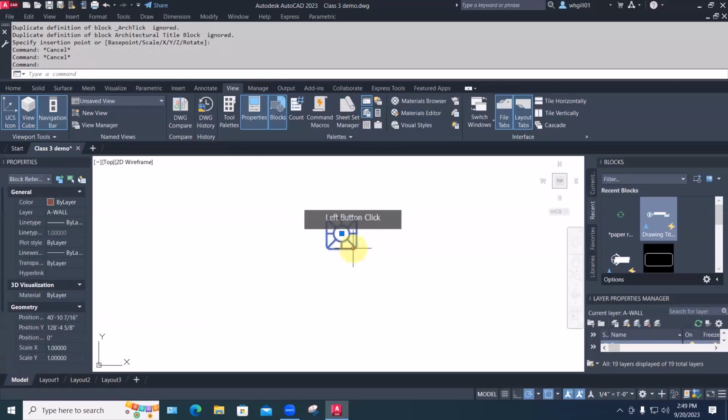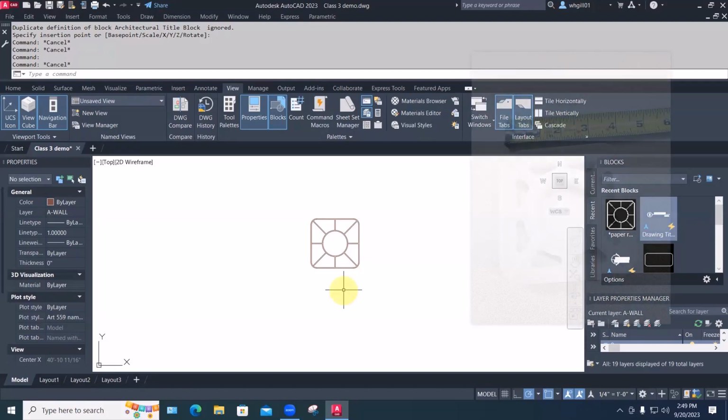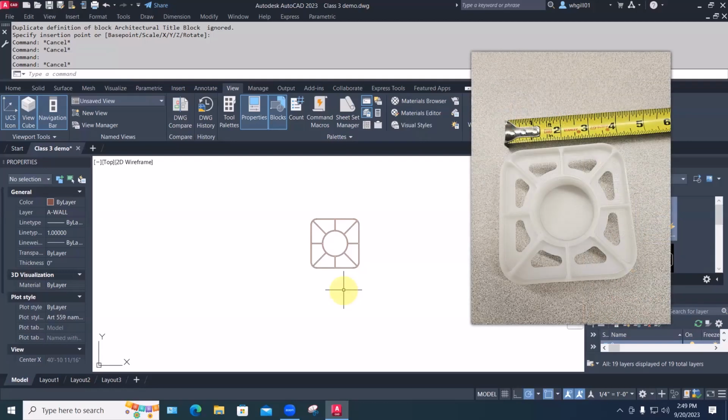And if we don't want it on, something I forgot? I should have drawn each of these objects on layer 0, which I did, and set their properties, color and line type, to ByBlock. So this would really behave well. So that's something I'll be looking for on your homework. Seeing this, I realized I forgot to put the holes in the plug. Always check your photographs.